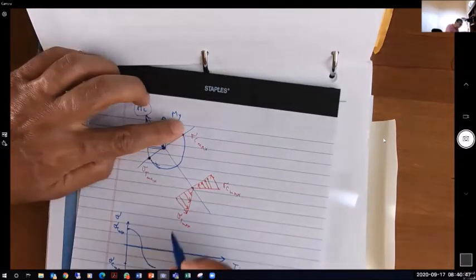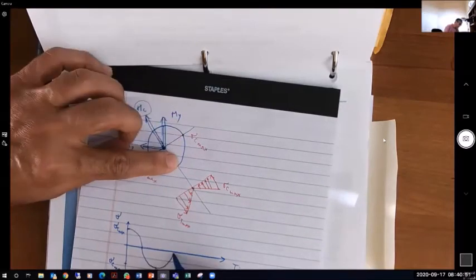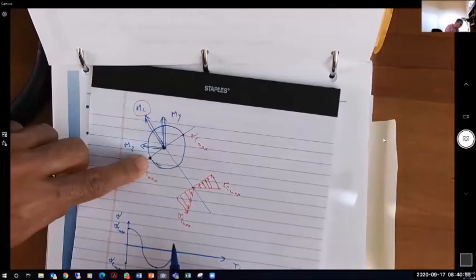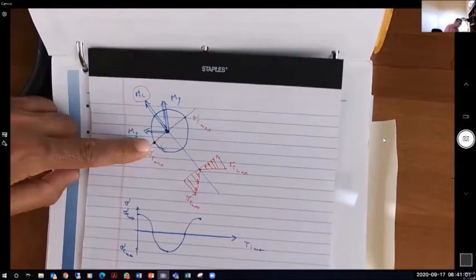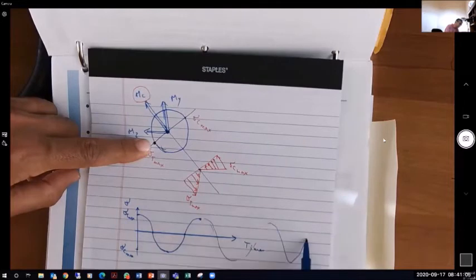And so on. It moves another 45 degrees and goes back to the neutral axis, to zero. It continues back to its original position to make it 360 degrees. It comes back to sigma T max. And of course, this curve will continue as the shaft continues to rotate over time.